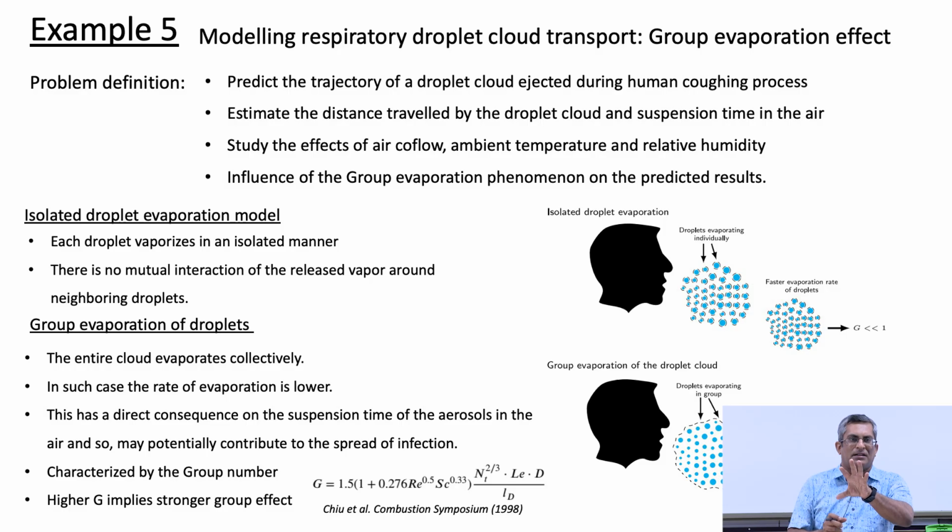When we inject the droplets in the form of a spray, most of the droplets burn as one cloud. That was their argument. So they developed a theoretical model, not by considering a practical injector, but by considering an isolated cloud of droplets. Earlier we had only one droplet. Now imagine there is a cloud of droplets, but that is isolated from any other cloud.